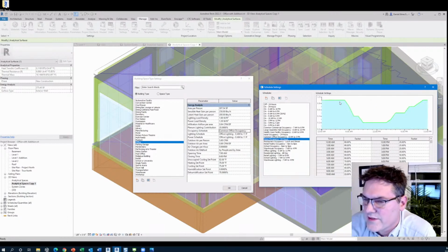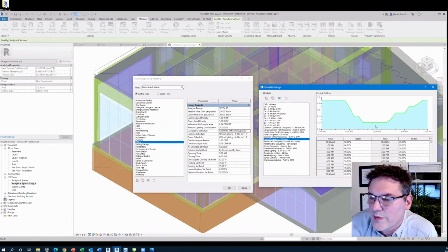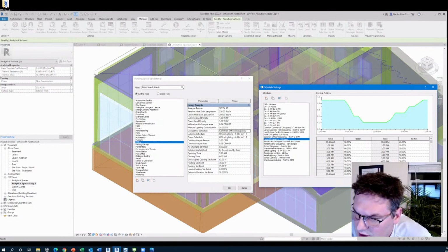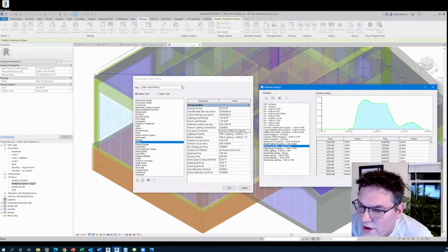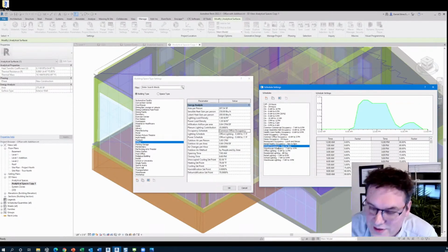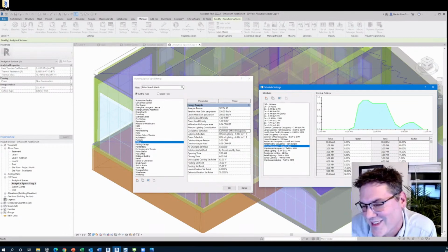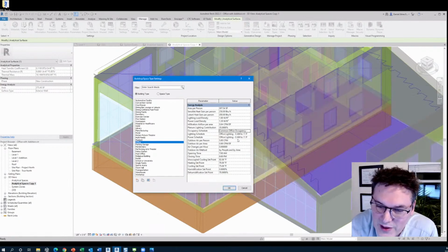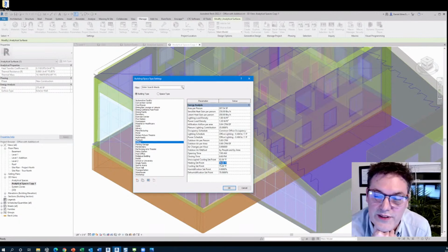So down here, there's actually residential home occupancy. So people are gone during the middle of the day, but home at night, right? Mm-hmm. Versus an office occupancy or schools. Interesting thing about schools is buried in this is actually that the U.S. national holidays, which isn't good for people outside of the U.S., but that's a handful of days in addition to what you see here. So there's a lighting schedule, a power schedule, the heating and cooling set points. You can adjust all of this, and this will be what is actually entered into the energy model.